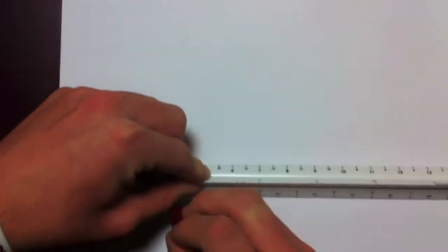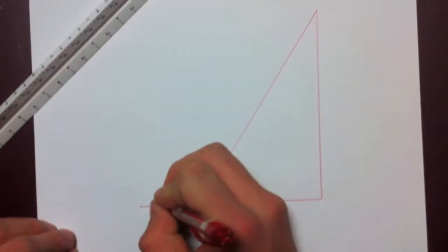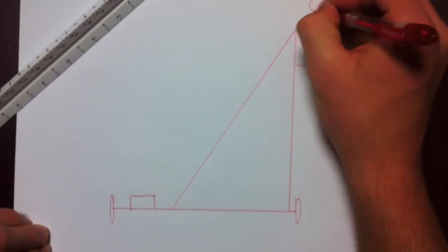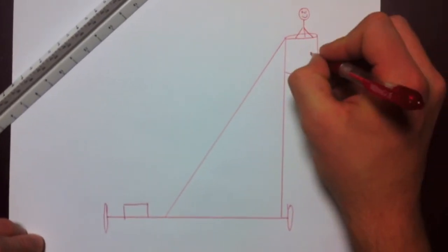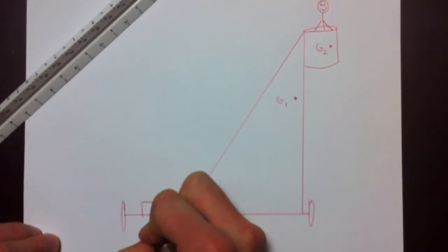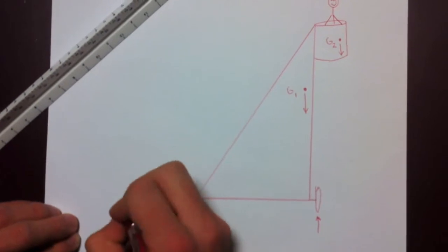The reason you fell is similar to this problem in the book. In this problem, a platform assembly has a weight of 250 pounds and a center of gravity at G1. If it is intended to support a maximum load of 400 pounds placed at G2, determine the smallest counterweight, W, that should be placed 1 foot to the right of B in order to prevent the platform from tipping over.